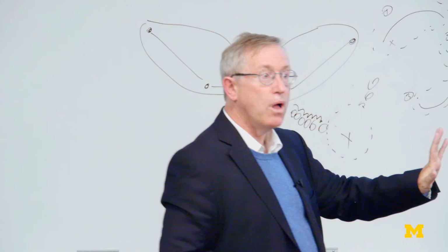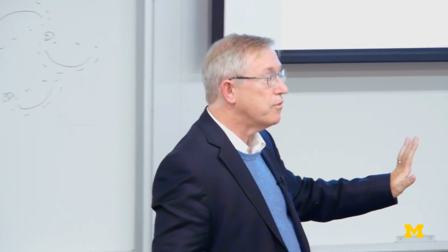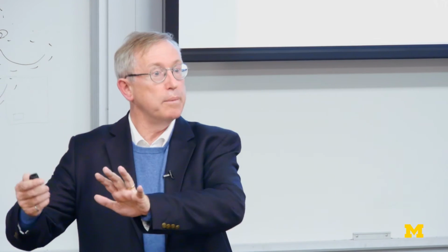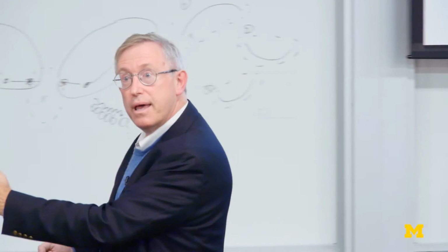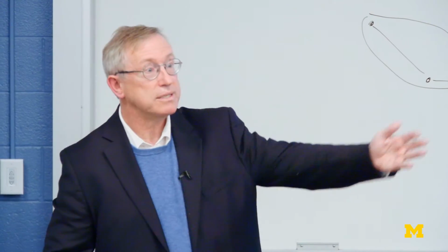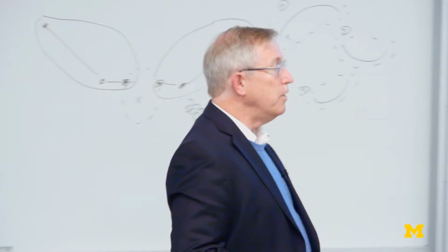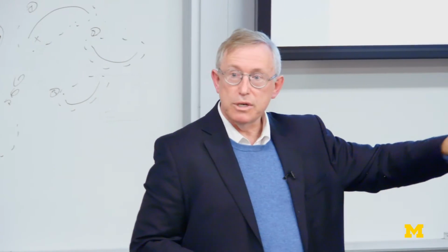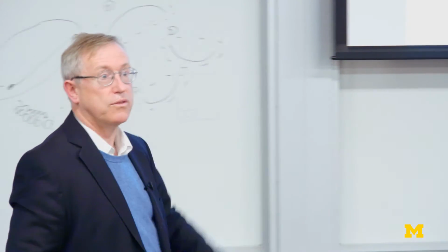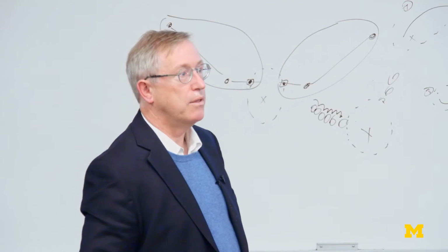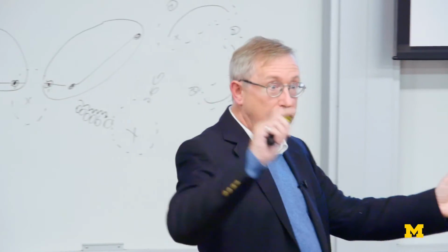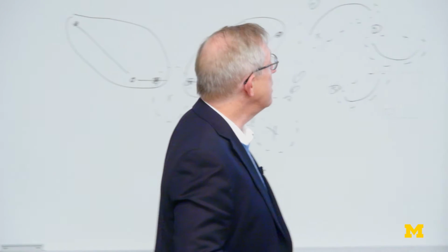You notice there's no loss. Remember, in our model we had no loss. There is an accumulation of energy because at each step we're adding a little bit of noise, so the signal is getting slightly more energetic as we go. But if there were no noise, it would be a perfectly noiseless, lossless type of system. You can actually show that not only is energy preserved, but entropy is preserved by this type of system. And this allows you to use the entropy power inequality to get a bound on capacity of this type of split-step model. I'll allude to that in a moment.